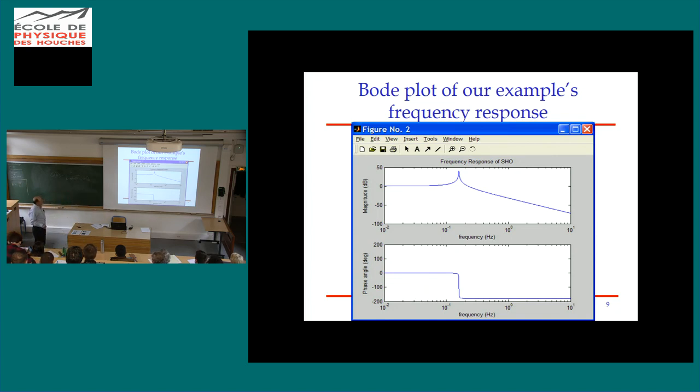What else can we see? Oh, Stefan mentioned this as well. There is a phase shift of 180 degrees as you go through resonance. The motion at low frequencies is in phase with the input. At high frequencies it is out of phase entirely, 180 degrees out of phase, and it falls through, and precisely on resonance, the response is 90 degrees behind the input, right?